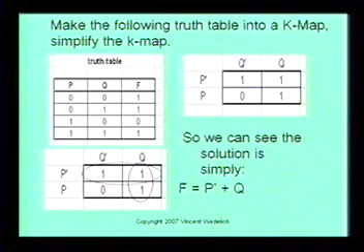It certainly doesn't look like it, especially because you'd think, well, if it was a 0, 0, and a 0 here, and this one was a 1, you'd say that's an OR gate. That's simple enough. But these are actually reversed on an OR gate, so it's not quite as simple. This is the K-map, and the way we construct it is not P, P, not Q, Q. So those are the 2 variables, the 2 inputs, and the result, or F, is inside the box.